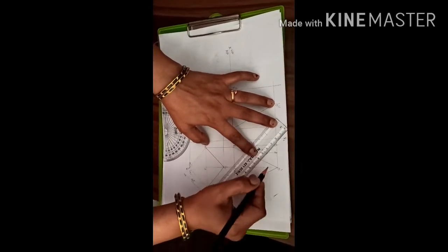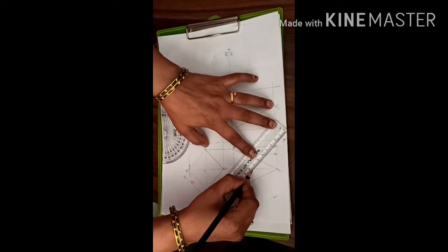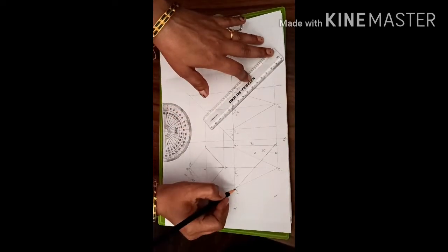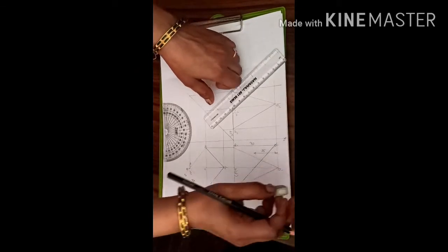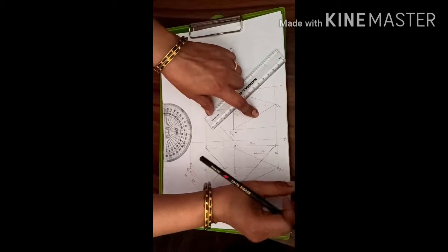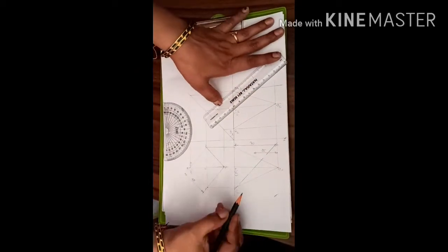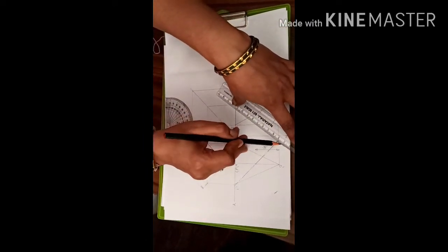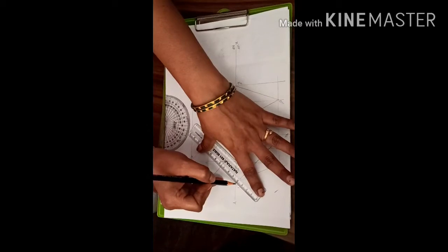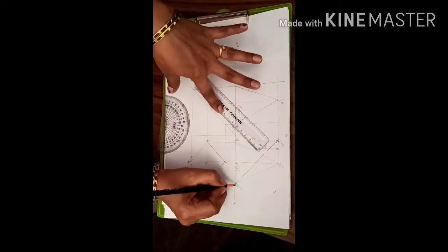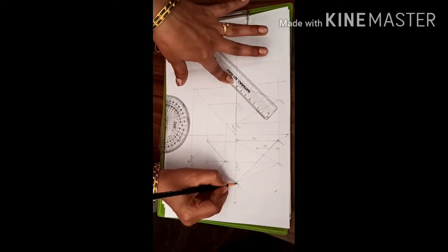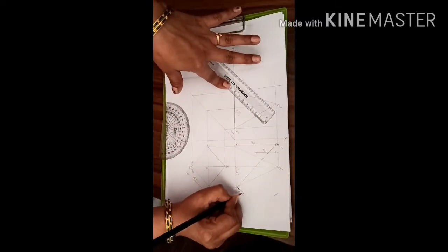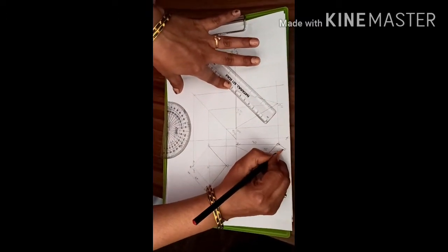So follow the convention for the section plane. One continuous line and one, right? So this is your section plane. So as I said in my previous problem, the section plane has to be indicated as SS. So show the arrows, draw the arrowheads, lines, and this is your section plane, and that's why I indicate it as SS.